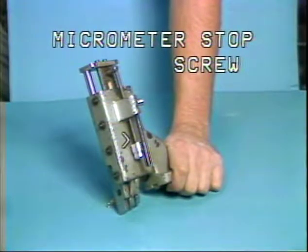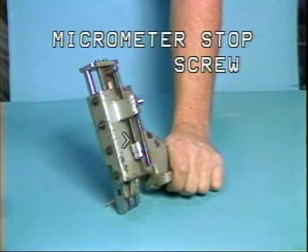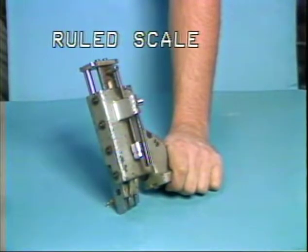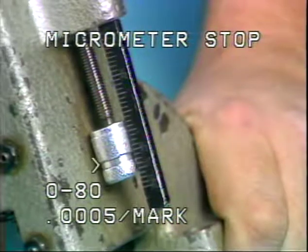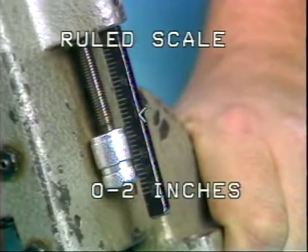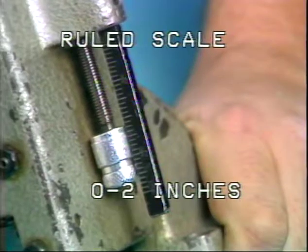This is the micrometer stop screw used on the 1-to-1 ratio feed attachment. The purpose of the micrometer stop screw is to adjust the length of the machined parts. Located here is the ruled scale. The purpose of the ruled scale is to indicate the approximate feed length setting. The micrometer is marked from 0 to 80. Each mark represents a 1/2 thousandth change. The ruled scale is marked from 0 to 2 inches.